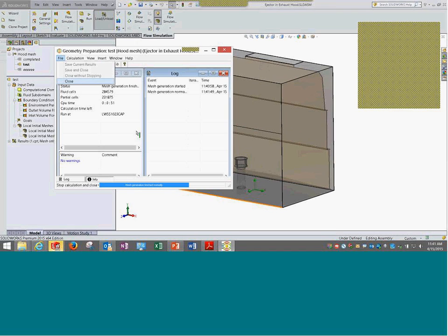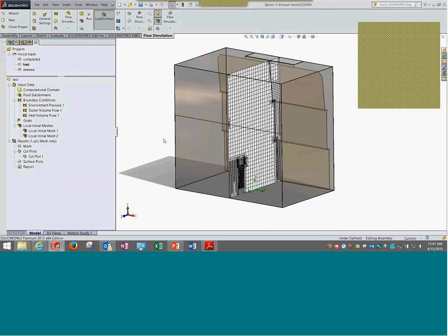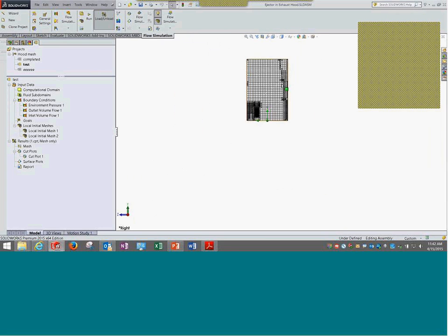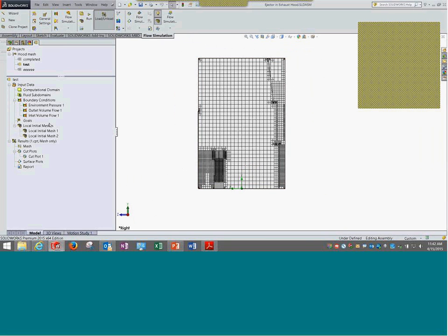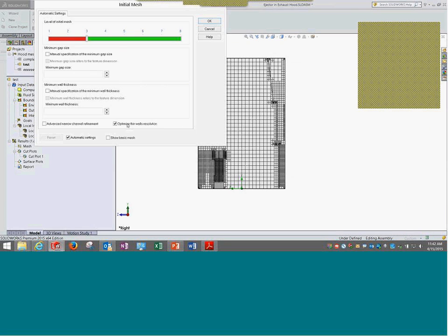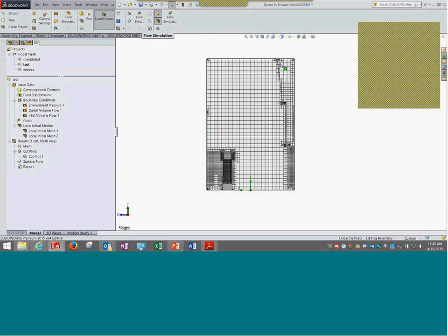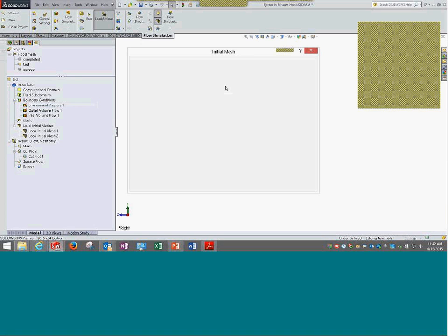Okay, I can stop talking. I can see the mesh. Let me show you the mesh. Here it is. The interesting part you can see is that even though I have used the initial mesh, I did not do anything else. I just used this one, initial 3, which involves resolution, and then it knows where the boundary conditions are. Even with this minimal input, it creates an appropriate mesh for it. We may not need to be worried too much about what to do.